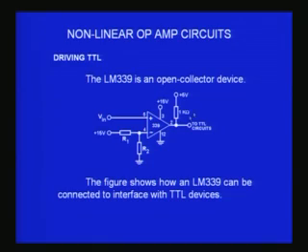So manufacturers have made comparators exclusively for comparing voltages, and not for amplification, and therefore those will have much better slew rate behavior. I have given one example, the LM339, which is an open collector device. The advantage of having an open collector device is to restrict the output voltage to any desired levels.